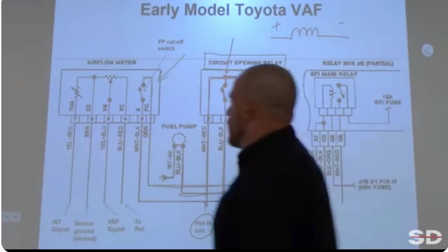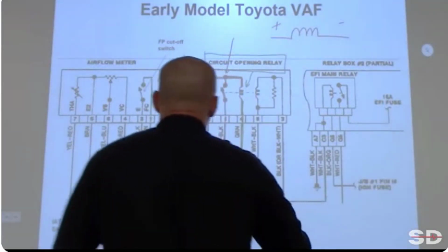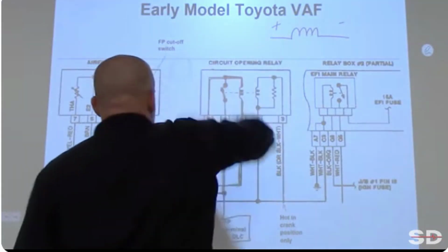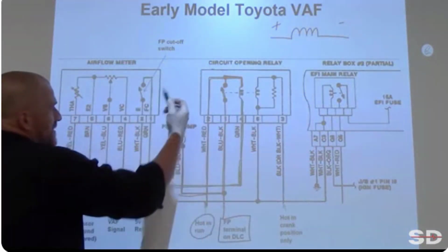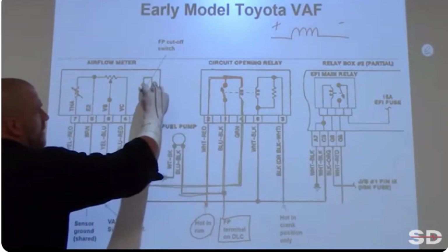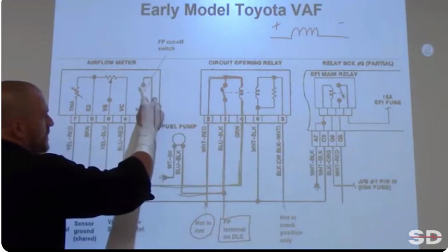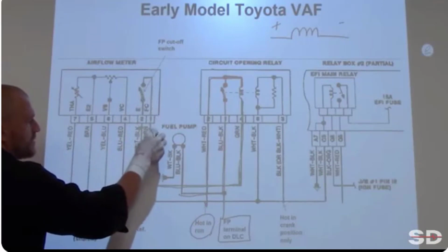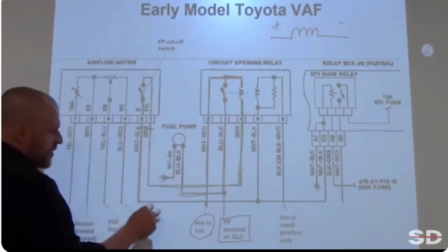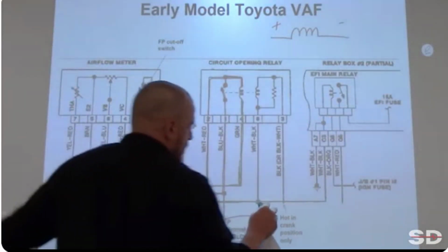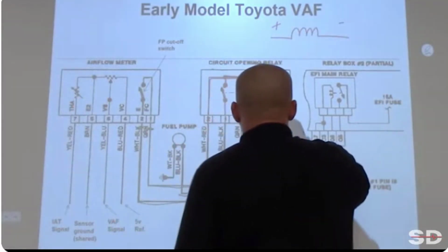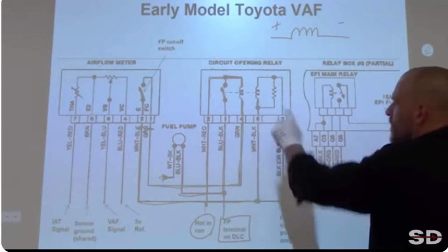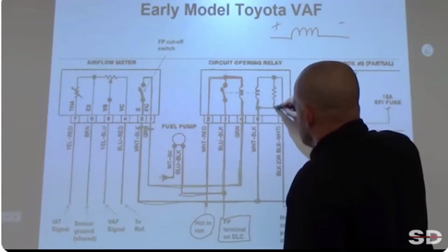Okay? So it has to go to ground. Where's this switch going to ground? We can stay the same color here. We don't necessarily have to switch, because once this switch closes, then these two wires are going to be the same polarity. Let's follow this guy, see where it goes. It comes to another splice. This can be difficult. Do we draw through this coil? Nope. Do I draw through this resistor? Nope.